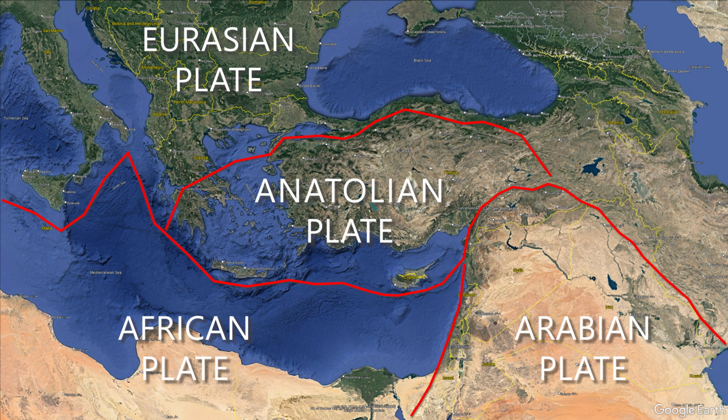This unique movement of the Anatolian plate causes it to slip along its east edge, or the East Anatolian Fault Zone, and also slip along its north edge, or the North Anatolian Fault Zone. The major earthquakes which have occurred in Turkey have occurred along either the East or North Anatolian Fault Zones. These fault systems have predominantly horizontal or strike-slip movements and produce shallow earthquakes which are particularly destructive at the ground surface. The tragic Kahramanmaras Earthquake, which struck on February 6, 2023, was along the East Anatolian Fault System.